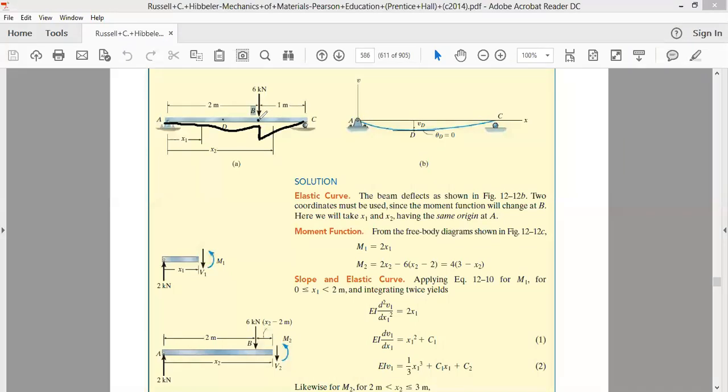At x equal to 1, the position of the beam will be specified by a single point, not by 2 points. So the clear idea is that the value of the deflection given by the equation applicable on the left hand side should be equal to the deflection at point B given by the equation applicable on the right hand side of point B. The two should give us the same values of the deflection. That means we have then obtained our next boundary condition.